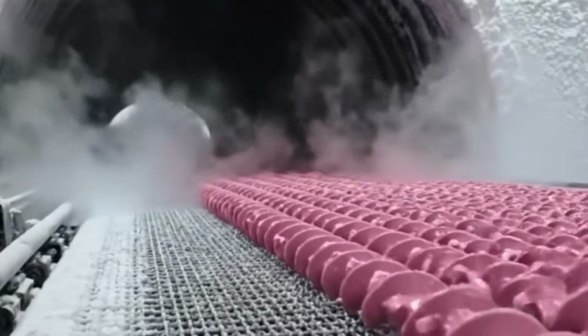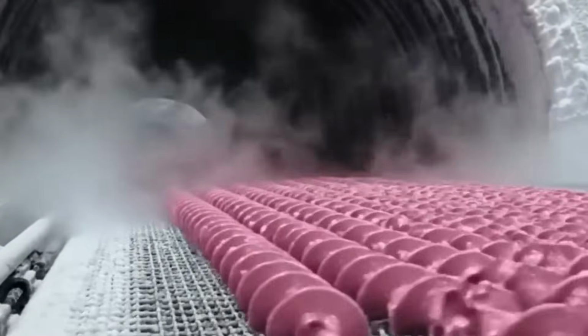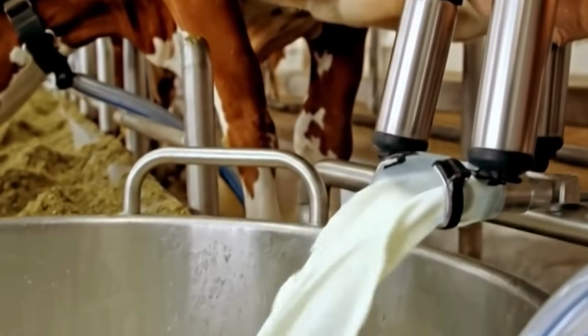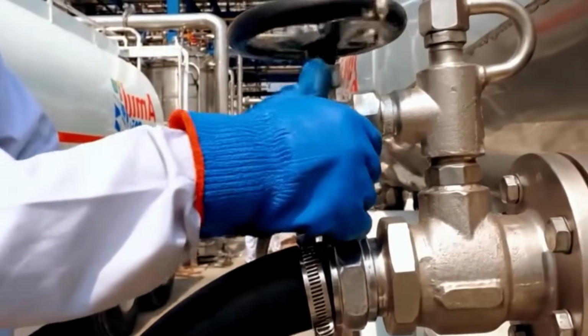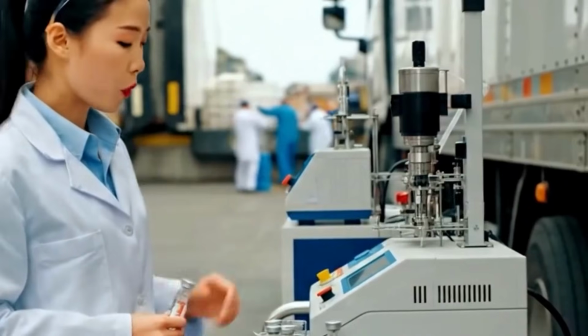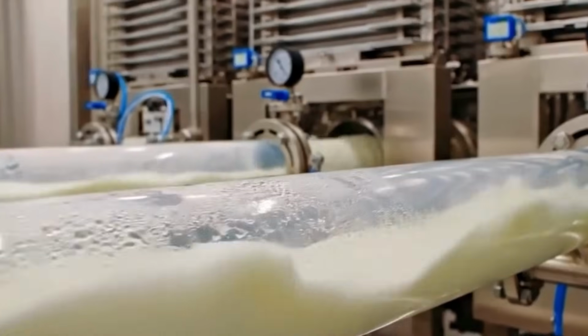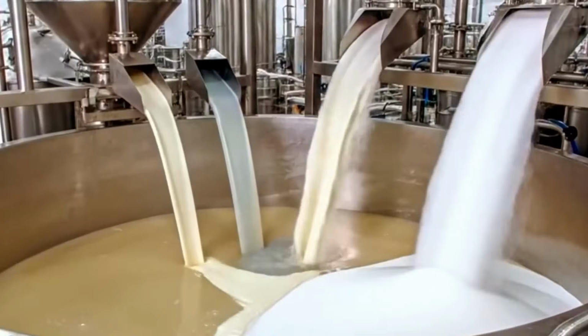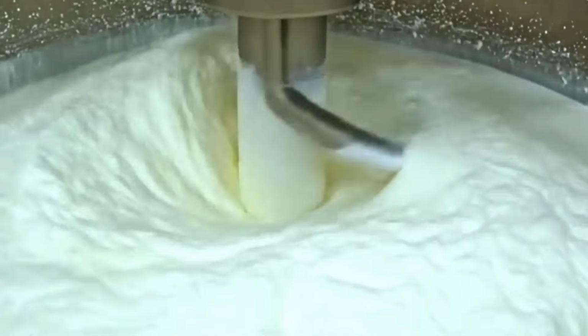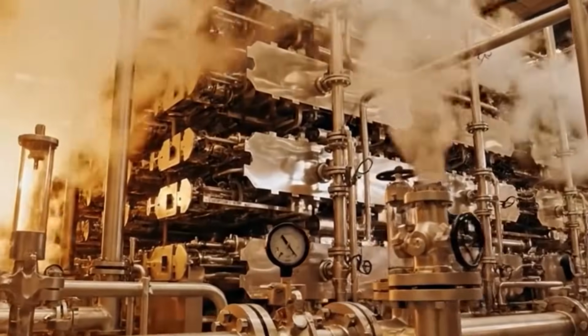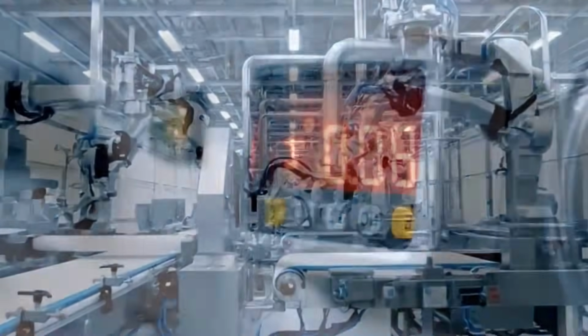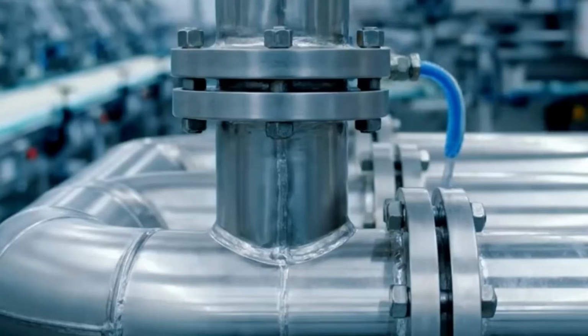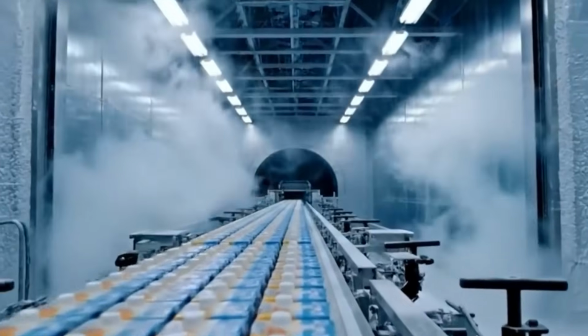Once the shape is stabilized and the product fully frozen, packaging begins. Products are loaded into flow wrapping machines or form-fill seal machines. Printed film is drawn from reels, formed around the product, and sealed using heated jaws and pressure. Modified atmosphere flushing may be applied to reduce oxygen exposure. Each package is marked with batch codes and expiry dates via inkjet or laser printers.